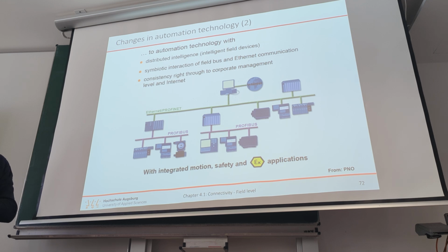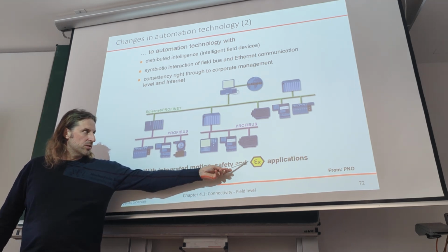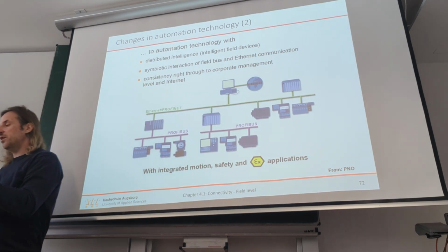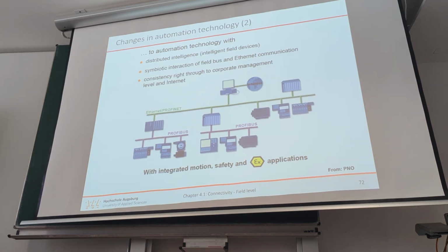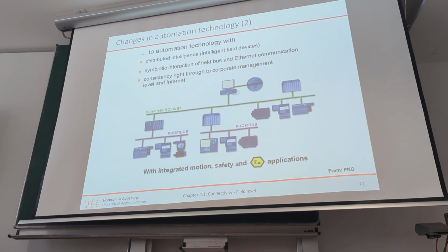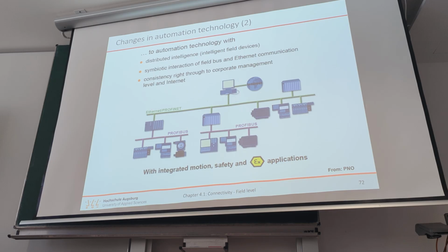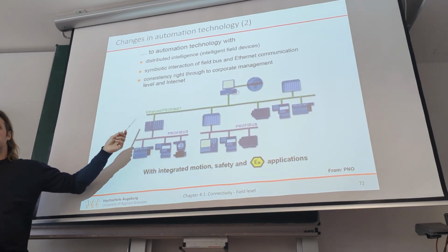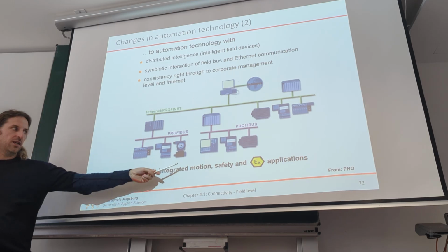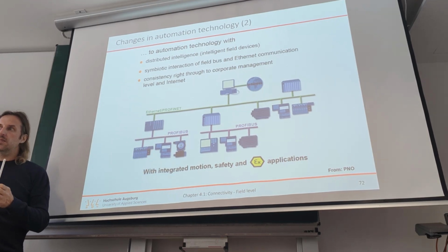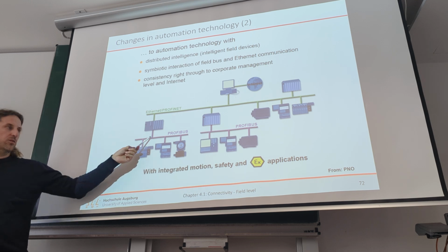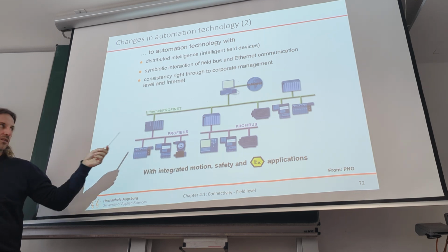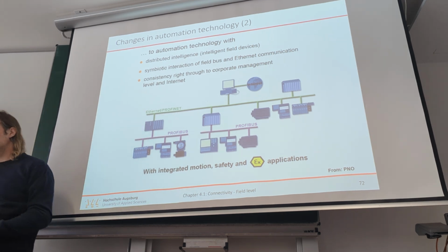Right now, the problem basically is that if you have a field bus cable and you cut it, there should be no spark that is strong enough to ignite the gas or whatever you have in your surroundings. That actually works in Profibus systems if they are X-safe. There you can cut the cable and the energy is absorbed in the cable fast enough to not create any sparks. We don't have the technology for Ethernet yet.